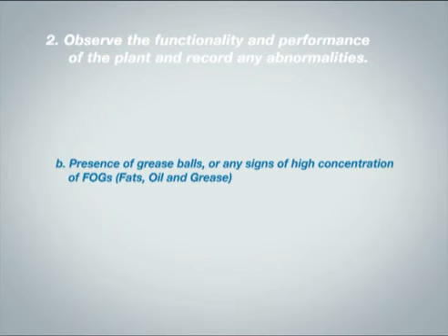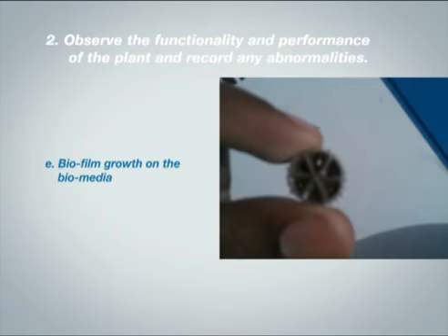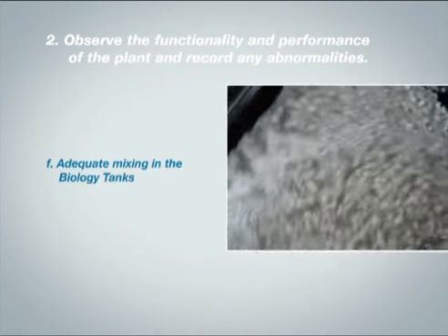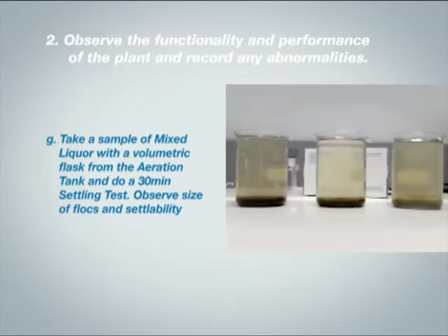D. Color of the mixed liquor in the biology tanks. E. Biofilm growth on the biomedia. F. Adequate mixing in the biology tanks. G. Take a sample of mixed liquor with a volumetric flask from the aeration tank and do a 30-minute settling test. Observe size of flocs and settleability.